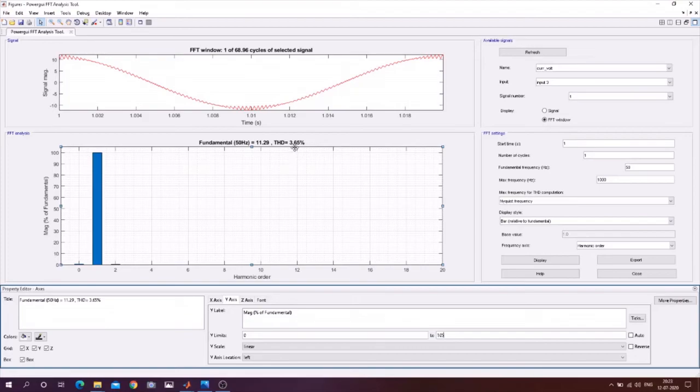So you could see that when we increase the THD in our reference waveform, that just decreases the THD in the voltage and current waveform. So space vector PWM produces output that is more near to the fundamental. We will just make a summary of these two in the next section for a better understanding.